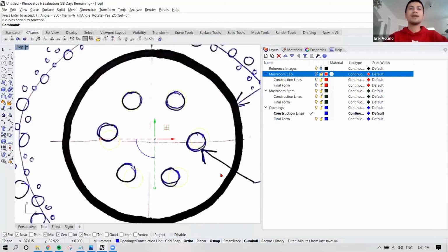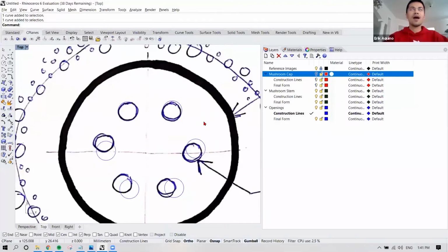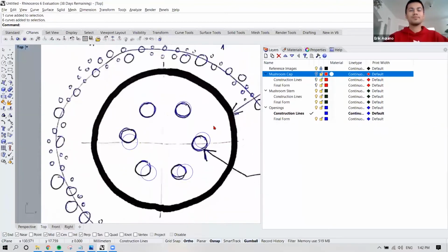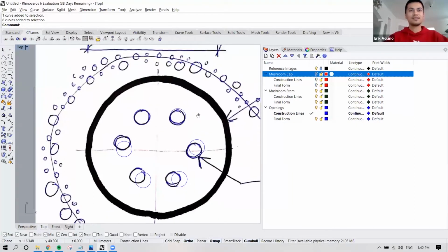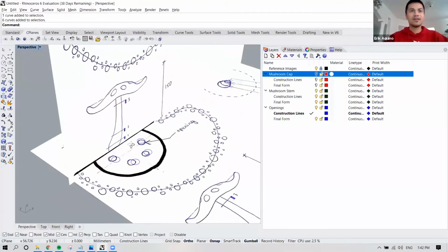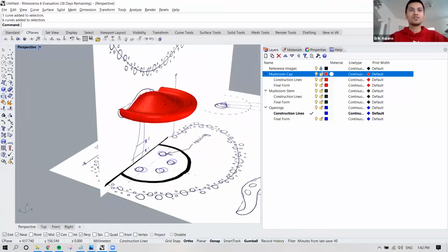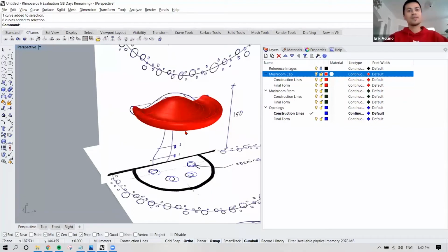And as you can see, my drawing is a little inaccurate. It doesn't follow exactly what our array polar command did, but I'd rather stick with the accuracy of this Rhino command versus my drawing. So we'll continue in that sense. As I mentioned, it's all on the XY plane, whereas we want these curves to be applied to this Z elevation for our mushroom cap. So one way we could do this is project these curves onto the surface above.